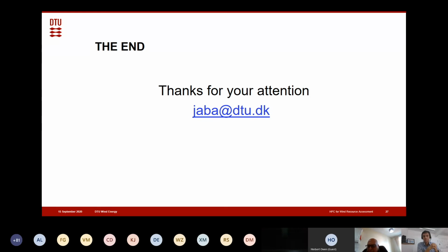We have a question from Peter Taylor. Could you explain ellipsis 3D versus high resolution nesting? Yes, I'll try that. So what we have with ellipsis is a resolution down to meters scale, whereas with the WRF modeling with the nesting, it depends. You could go down to 9 to 3 to 1 or even to 333 meters, if you like. It's a question of where you want to pass the mesoscale modeling information to the microscale, to ellipsis.